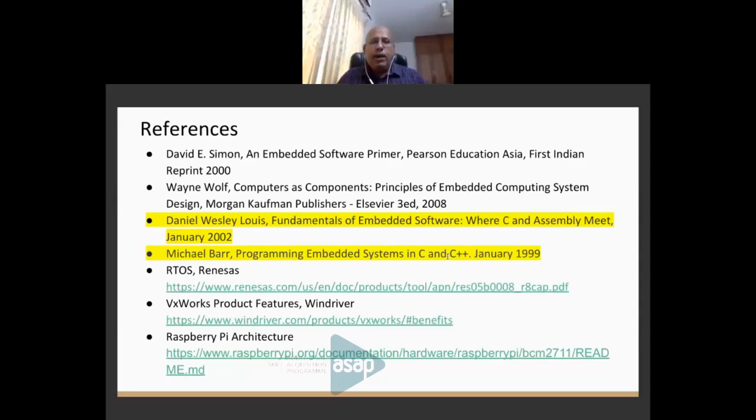Yeah, so the last point I didn't get, but let me tell you, in an operating system, typical operating systems support 1 to 255 priority levels. While you architect your application, you will split up the application into multiple tasks, and then you will understand which are the tasks which need to have the highest priority. So you will give these priorities in a static manner while you design the application.